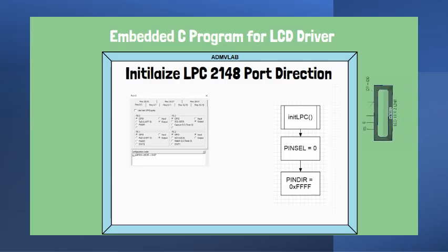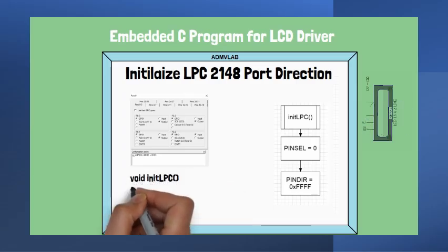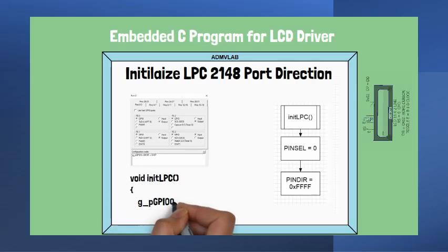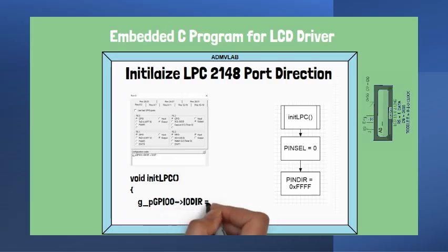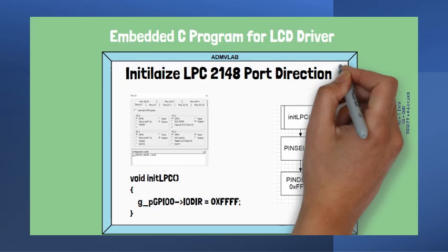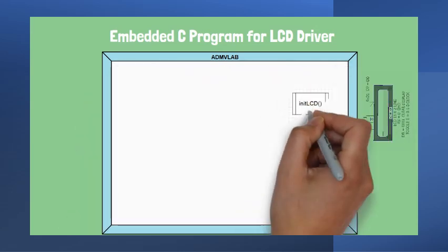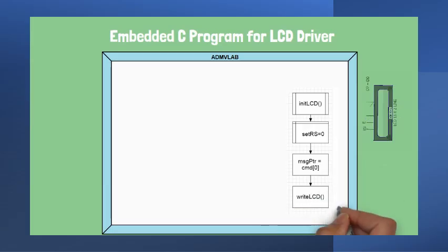We will be needing 16 I/O pins, 8 for driving the LCD controller's data bus, and 3 more pins for handshake control. The bits will be the register select bit, the read-write bit, and the enable bit. The enable bit strobes 8-bit I/O data into the selected register. We will configure the LCD module as an 8-bit data interface with 2 lines of display.